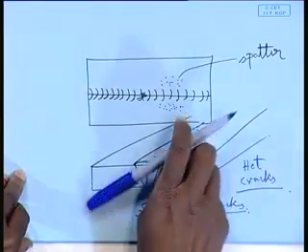Solidification cracking, that means as if during the process of solidification it has cracked. So generally surface cracks are due to solidification cracking. They are generally hot cracks. Well, what happens? Because of stresses, because of unfavorable thermal stresses taking place, the structure is unfavorably restrained.